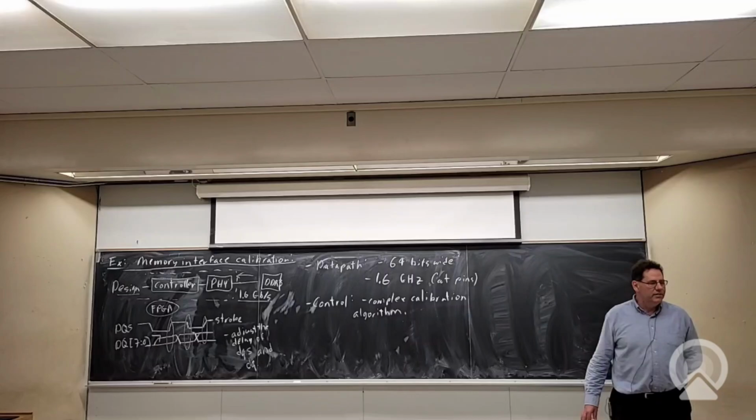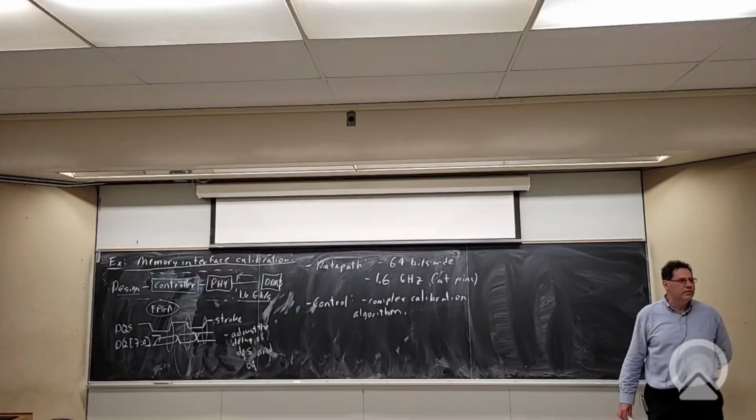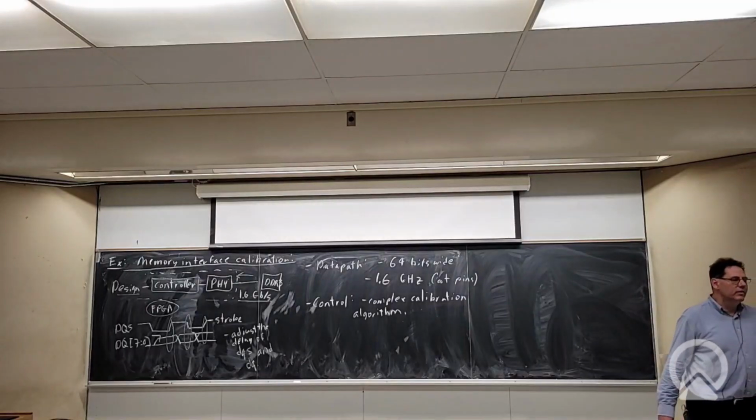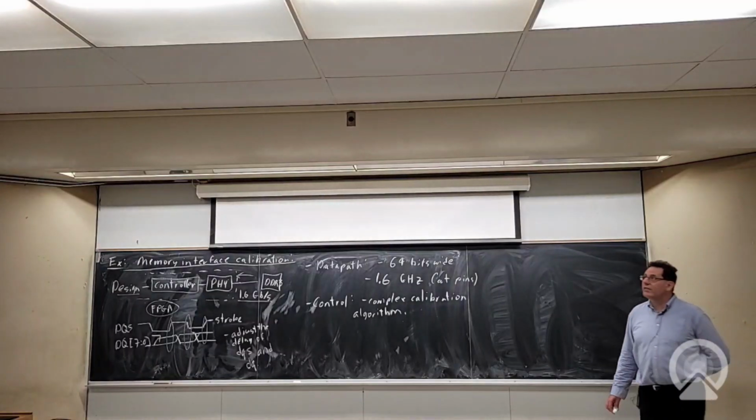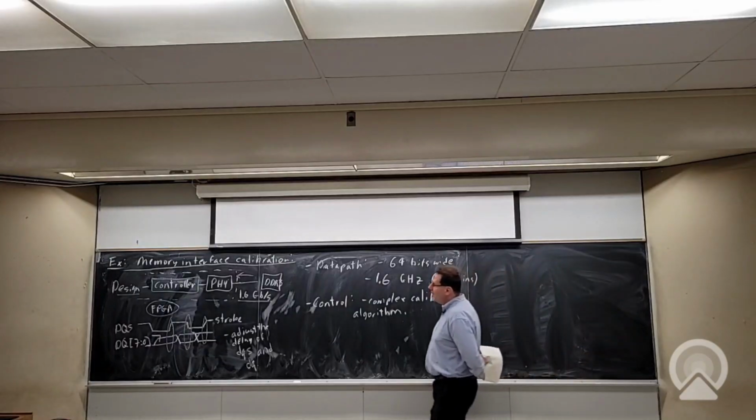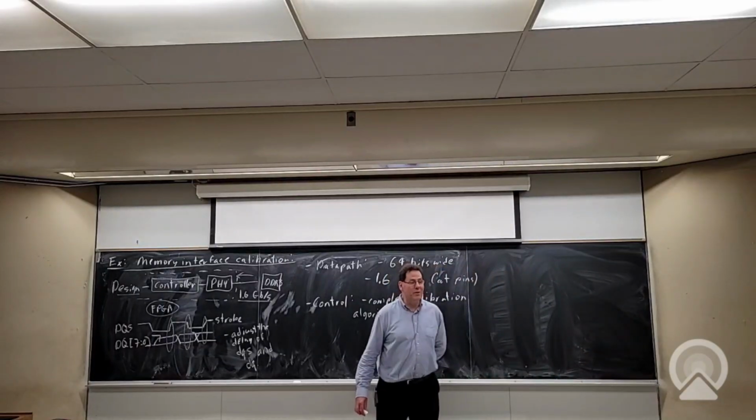Yeah, what I'm thinking about is if you're trying to line up the DQS with DQ, what if you have the trace when you send it to DDR, if you can measure a returning trace back to some control logic that measures how much latency was the round trip, and then adjust based on that? Is that something that they use for that algorithm? Yeah, let me think about that. I mean, the algorithm's complicated, so I don't even know if I can describe all of it.